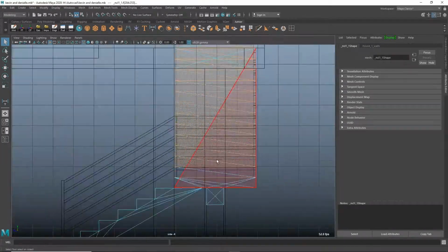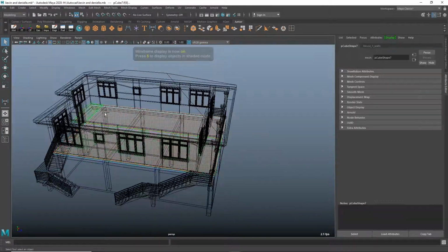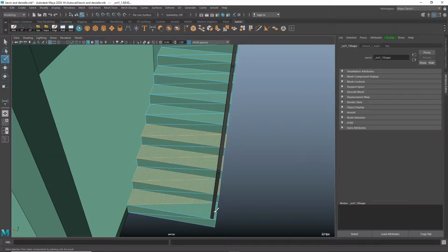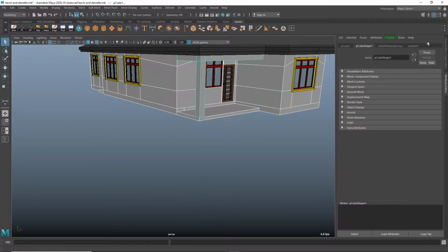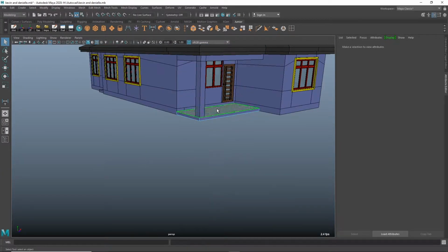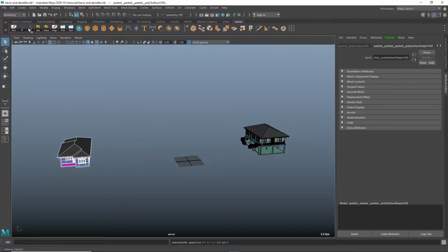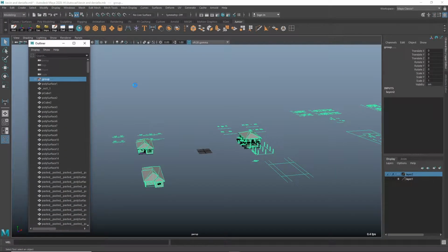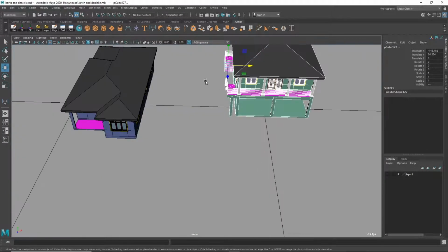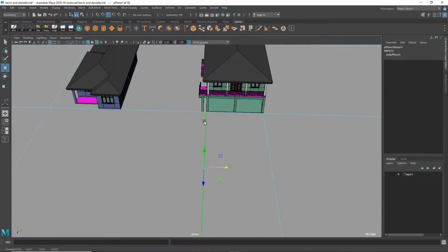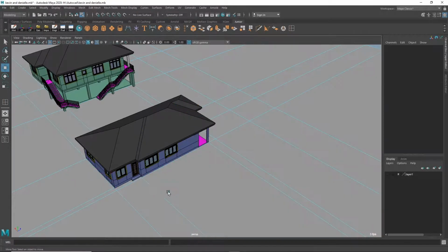So at this point I'm just adding different shaders, so they would be individual materials in Lumion. That pink is for the tiles, and I'm doing each one of the buildings separately, so the walls would be a different color. Certain things would remain the same, like the roof, the windows, and the glass would be the same, but the wall color itself and anything that needs to be completely different would be on an independent material.